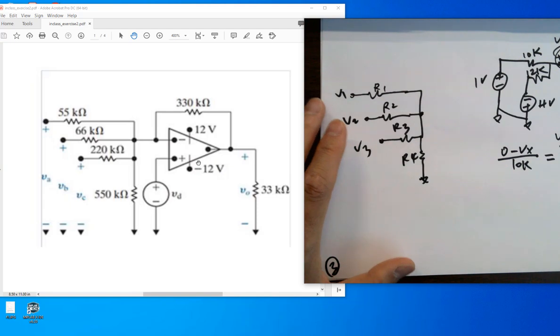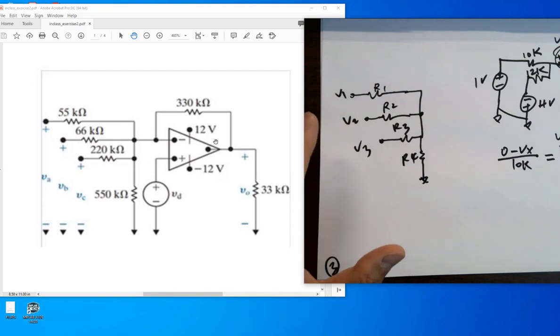Another thing. So plus minus 12 volts, does that make sense to you guys? It's a dual power supply, right? This is what we usually do in the lab or in the textbook. So we don't use ground, but usually in the real world we use a ground. So in that case, you have to add a DC offset. But I think it makes sense because you don't want to confuse the beginners too much. So we are getting rid of the DC offset, not lifting the signal to 50% of the voltage range. Instead, we just let the signal swing around 0 volts. So that's something we don't have to worry about. I know it's complicated, but we don't worry about that.